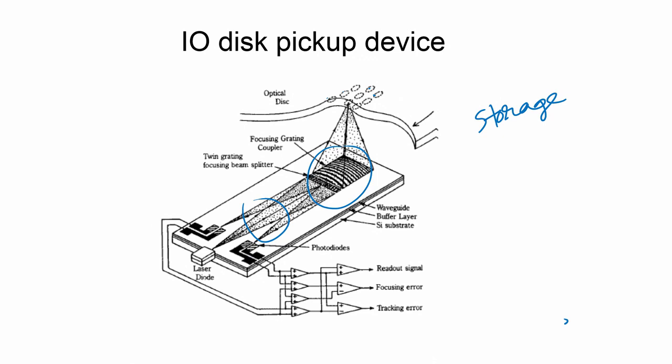You see the light is focused onto this grating in a planar way. This is a planar waveguide, and there is a relief grating here which can focus the light onto these bits, and the received signal is also received by this and directed into these output ports. There could be photodetectors here to convert the optical signal into an electrical signal, and later on you can do a lot of processing at this point.